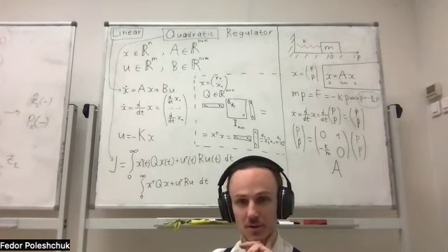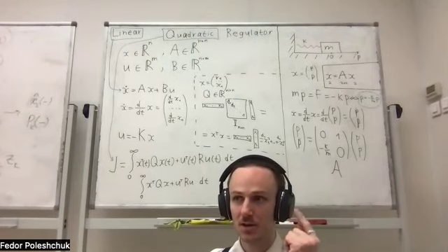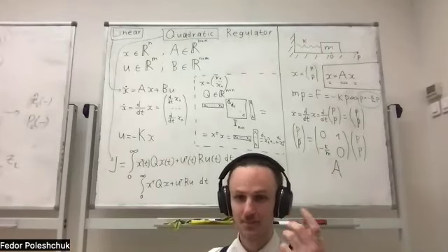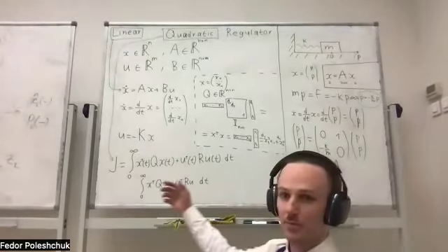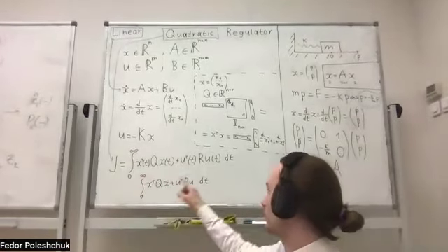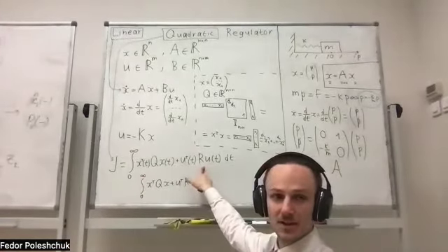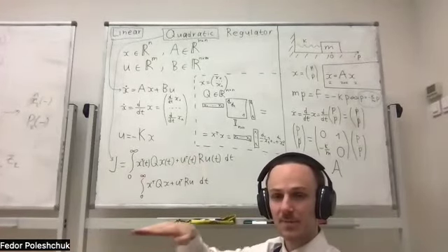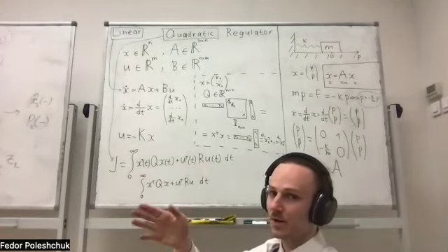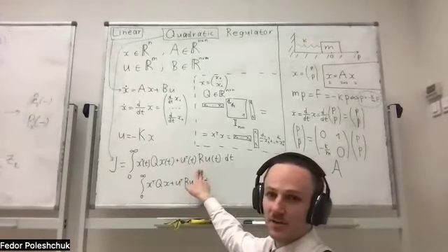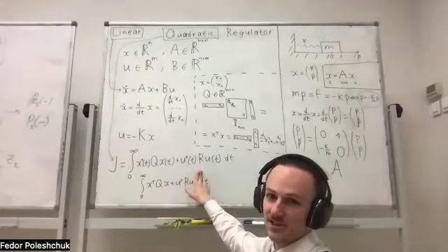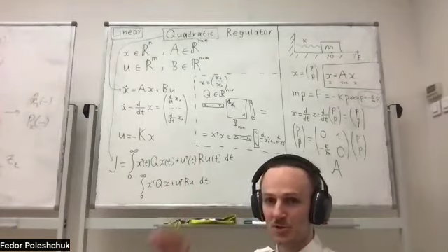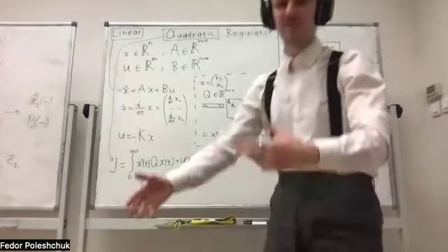Those parameters are really up to some kind of tuning, but it's very different from tuning the PID control, because here we tune our functional, our cost. Well, if we're dealing with, say, a robotic vacuum cleaner, and we know that it's moving linearly with very high velocity, and it's rotating very slowly, we would like to save some effort with the rotation because it takes a lot of time and it's boring and tedious, and motors wear out, or it's differential drive, right?